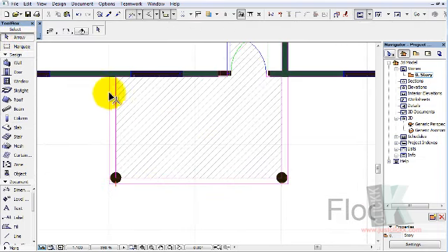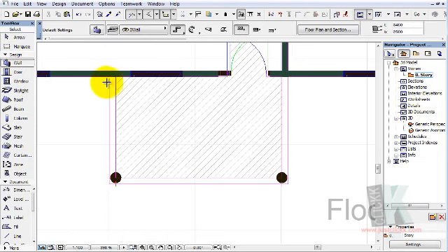Now we need to create a suspended wall that would turn around the columns here. So let's go ahead and pick the wall. And on the wall section, how do we want our walls? We want our wall continuous. So pick this option. You can click, hold, and then select this option, which gives you the continuous wall.